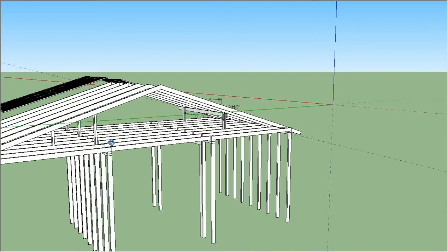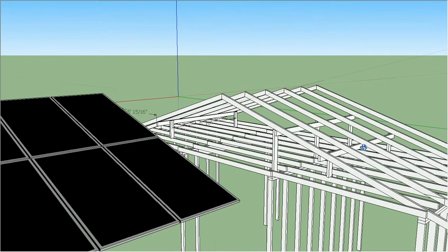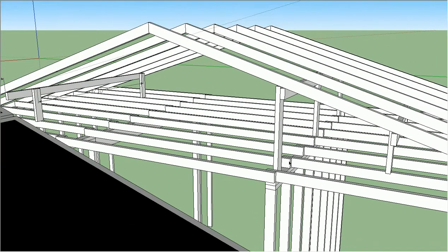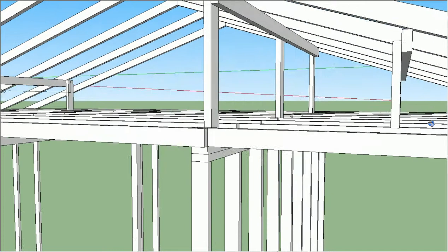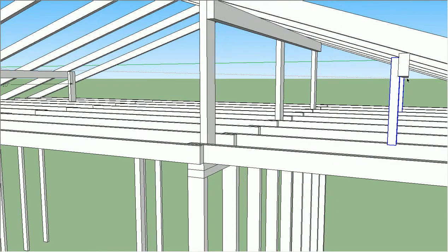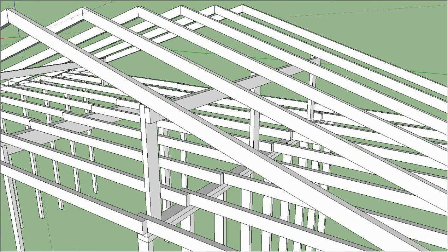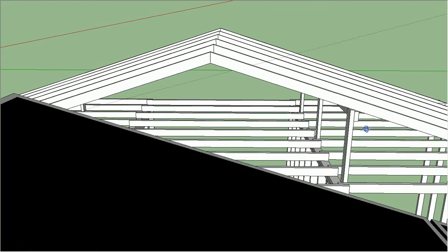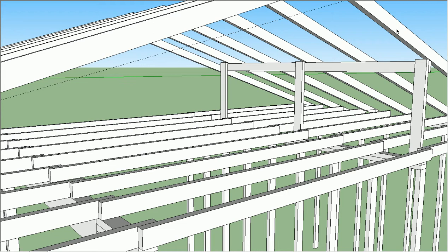So the other side of the structure is a little bit better built because these struts land directly on the wall. So if this purlin wasn't here, in fact, that purlin is not there, this is the simpler case where all you need to record are the size, the spacing and the span of the rafter and the purlin. And also you'll note that because my rafters are 24 on center, and you can see this is 2 feet here, 2 feet here, this purlin is spanned 4 feet. And 4 feet on a 2x4 purlin is usually just fine.